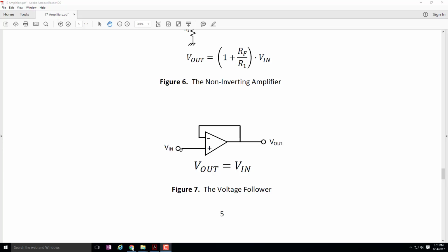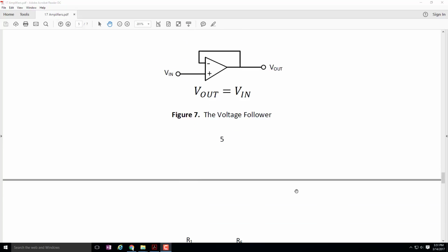But notice that there's one other thing that the voltage follower does, and that says, I'm not going to take any current from Vn. So I can sense what's going on with Vn, and I'm not going to disturb it at all. If I just had a wire, I have no idea what's going to happen with the current that's going to be drawn from Vn, and that could change the behavior of the circuit. But because I'm taking this directly into an input of the op amp, this current is 0, and therefore I'm sensing the voltage, but I'm not affecting the voltage. And the Vout then will just simply follow Vn, and I can do whatever I want to over here because the op amp can deliver enough current to be able to power an awful lot of different things.